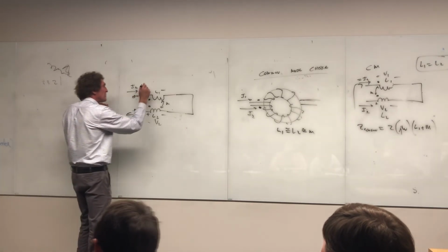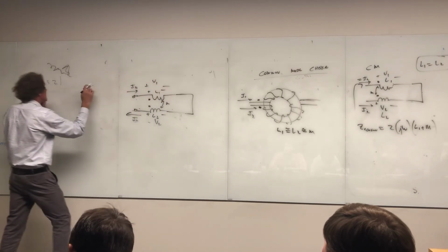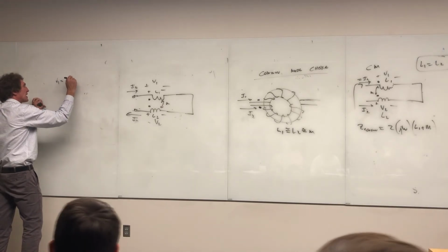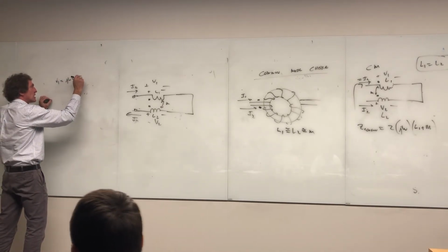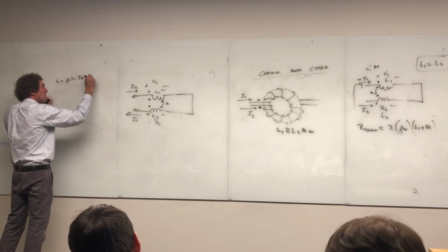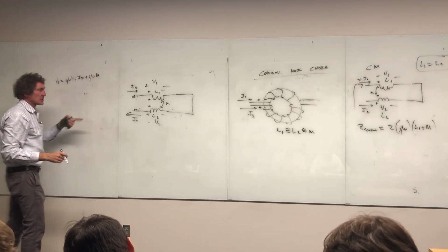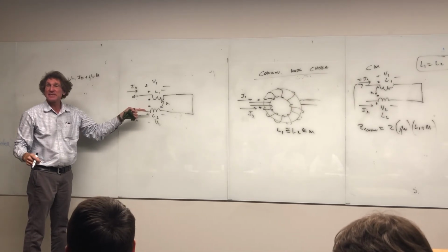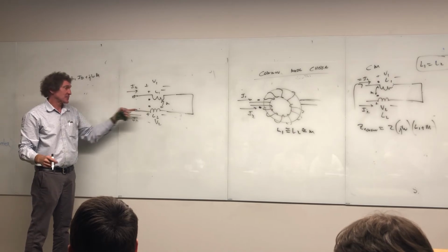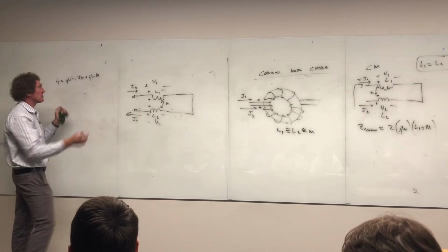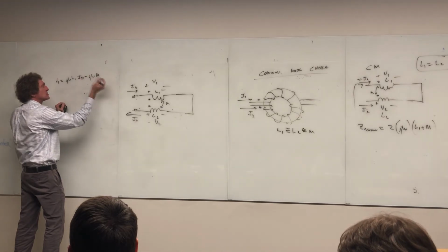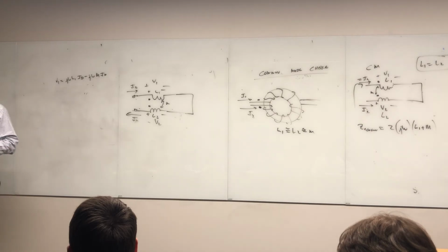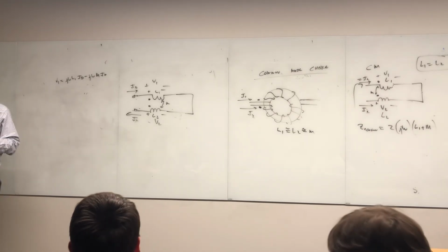Well, this is voltage V1, right? So V1 here would be equal to J omega L1 times I differential, right? Then it's plus J omega M times the current entering this one. Do you all see that that's minus I differential now? It's negative, right? Because the current's not entering, it's leaving. The way you adjust for that is put a minus sign. So this is really minus J omega M I differential. Can you all see that? Are you with me? And this is the bottom line of this.